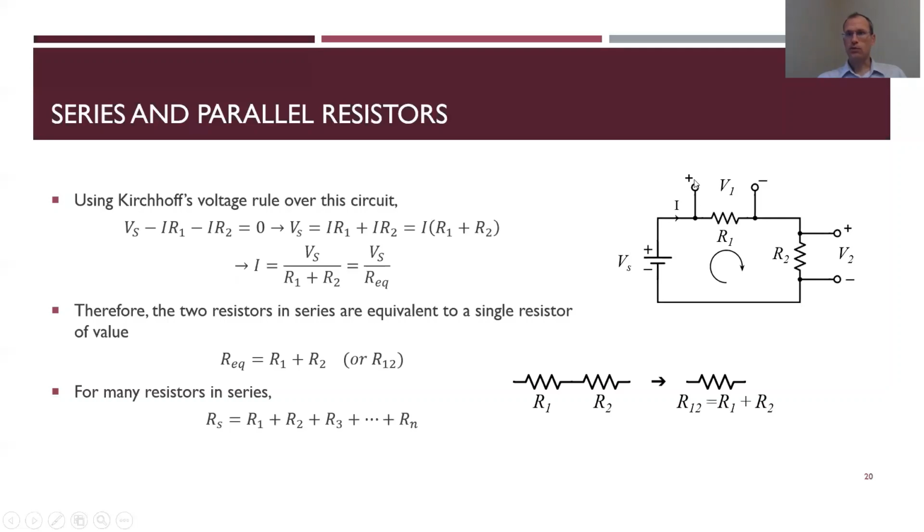Then it has some voltmeter essentially. So this V1 is measuring the voltage across R1. So it's basically telling me how much voltage of this Vs that R1 is taking up. Some other voltmeter V2, again, telling me how much voltage of this Vs R2 is taking up. So based on, again, Kirchhoff's loop rule, I'm going to have that V1 and V2 have to add up to this Vs, or more officially, minus V1 minus V2 plus Vs equals 0.